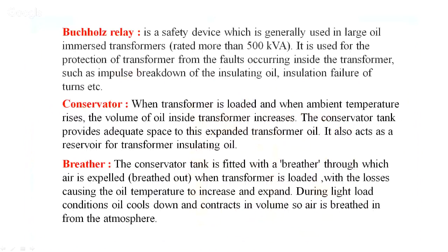Now let us understand, just for knowledge sake, what is the function of this Buchholz relay? Now this is a safety device which is generally used in large oil immersed transformers, which have a rating of more than 500 kilovolt amperes. It is used for protection of the transformer from the faults occurring inside the transformer, such as impulse breakdown of the insulating oil, insulation failure of the turns, etc.